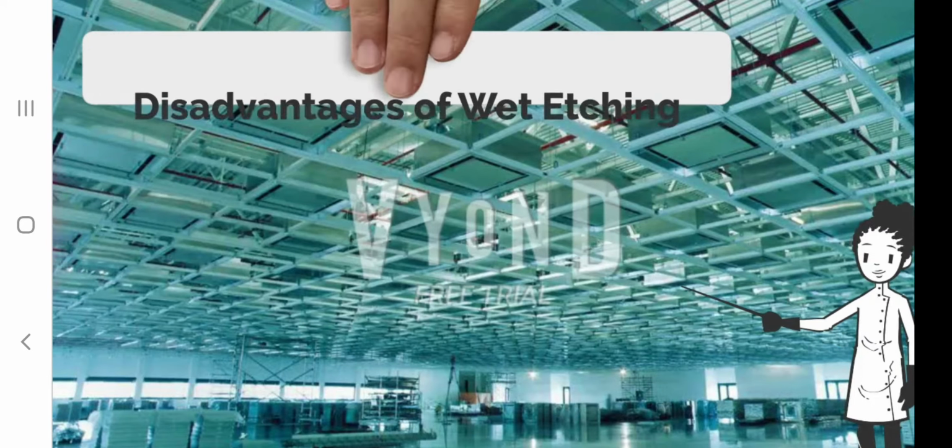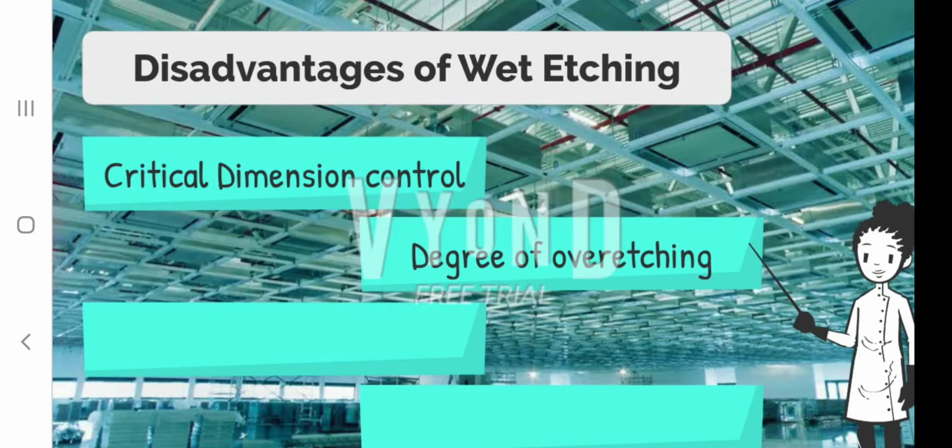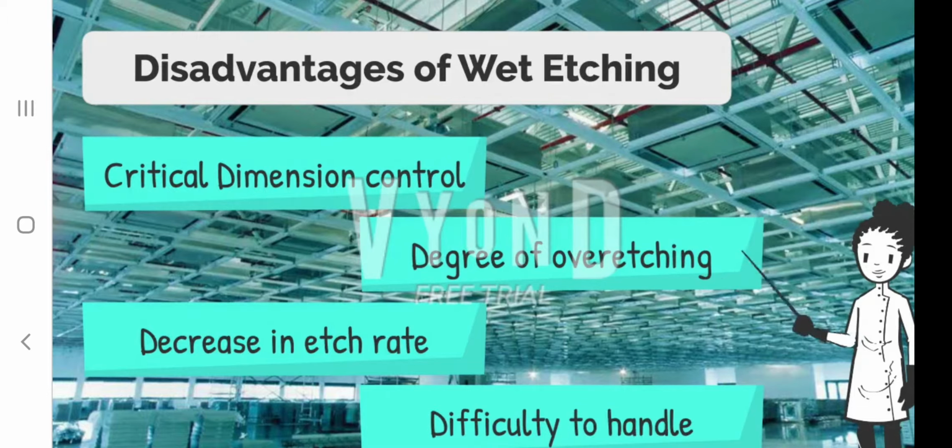Disadvantages of wet etching are complexity to control critical feature dimension and the degree of over-etching, decrease in etch rate as reagent solutions are consumed over time, difficulty to handle not only because it uses pure hazardous chemical, but the film it produces is also toxic.